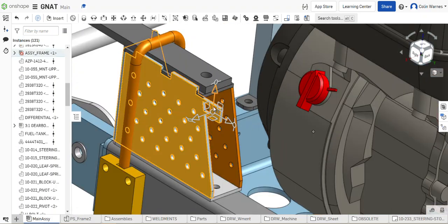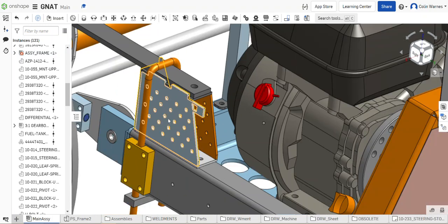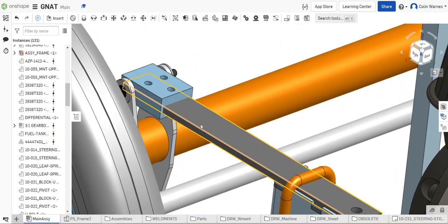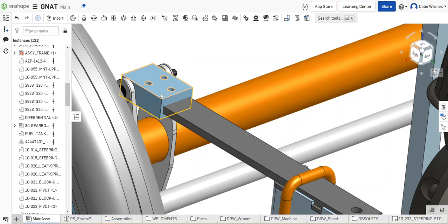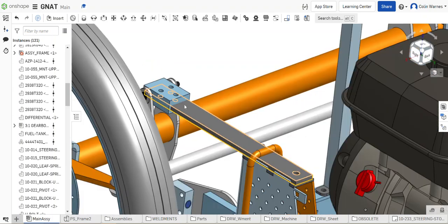This little tab here was designed specifically for the forming and bending of this sheet metal. Once it was bent up, I cut it off, and the whole assembly was welded together. You'll notice in here that the mounting block is kind of passing through the spring steel. I did that to help do some preload to the suspension.